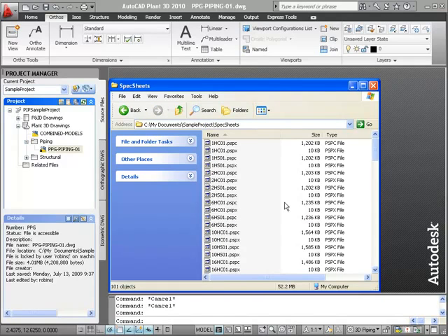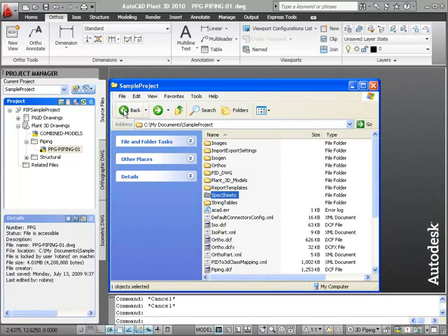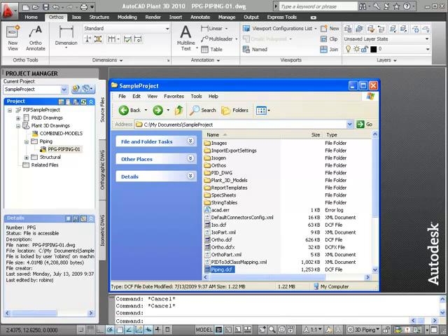When you create a project, all the specs from the AutoCAD Plant 3D 2010 directory under Program Files are copied here. This directory controls the specs available for the project, and you should replace them with specs that you create according to your project requirements. There are also a number of other configuration files found under the base project directory.